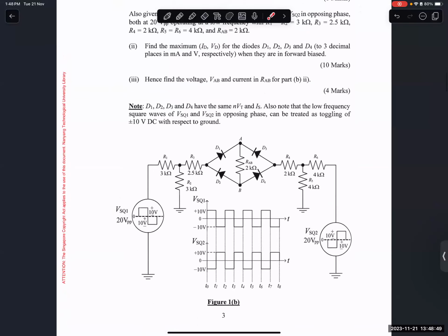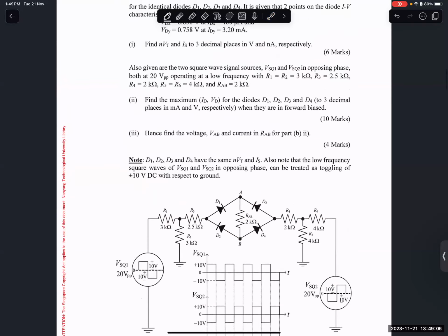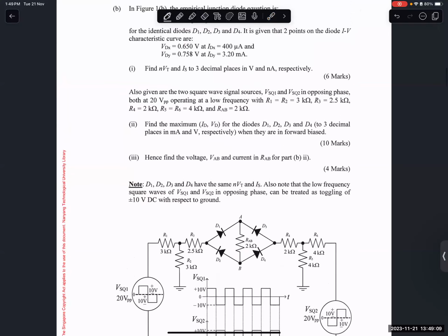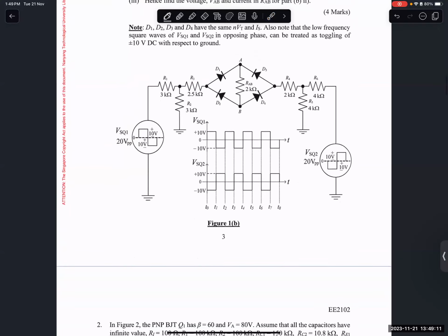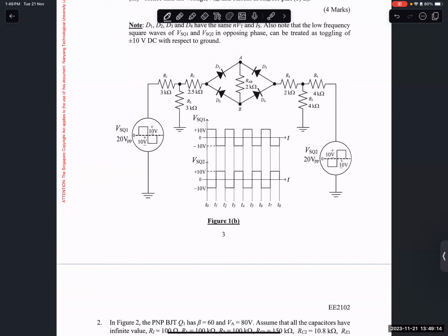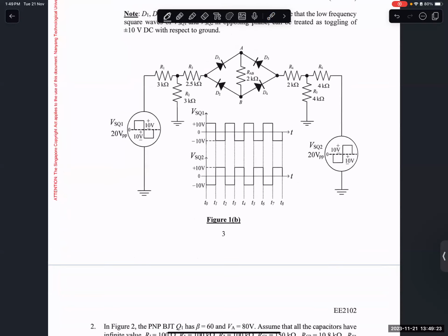You do the first part. At first the current will go like that, right? Then after that, when it's negative, you go like that. So we need to do 2 calculations, but actually it's the exact same, we just do the opposite. So we just choose one. Okay, so let's do the equivalent circuit. So what is the equivalent circuit? Oh, super easy. Okay, so your RTH is 8 kilo ohms.